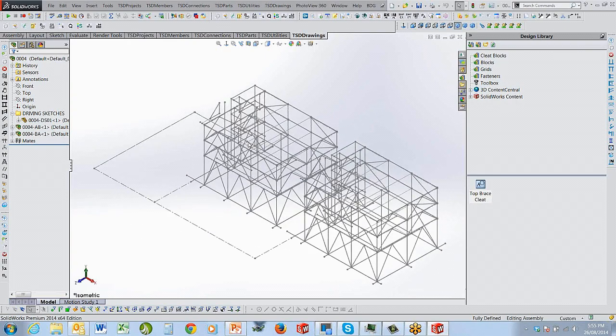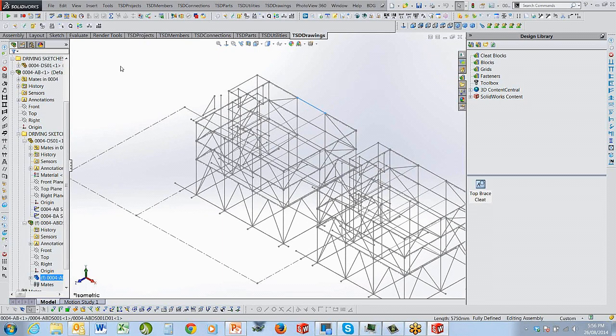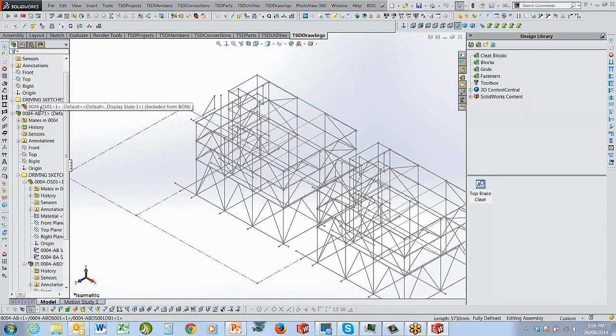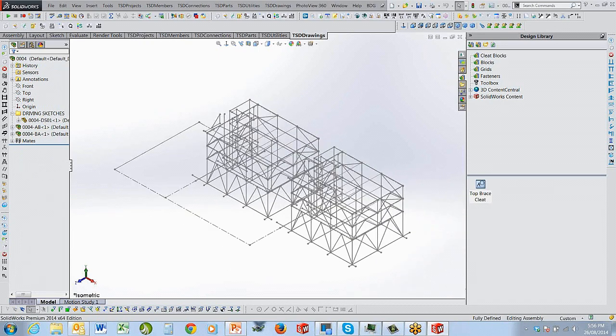The driving sketch that's associated to this frame could also be created and put into your civil or your piping, so that you've actually got the frame there to which you can attach a new driving sketch part and then add the piping to. So that's a really good setup for people who work in multi-user environments.